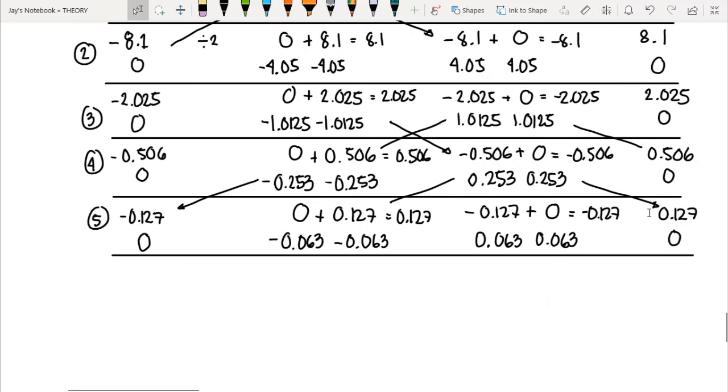Now for our 6th cycle, we stop when we have a 0 decimal places. But in this case, we can actually end, but I guess the unbalanced moment is quite too large for me, but this is your preference. But I would suggest that you end when we have 0 on the decimal place. Now in this case, we can carry over the moment.